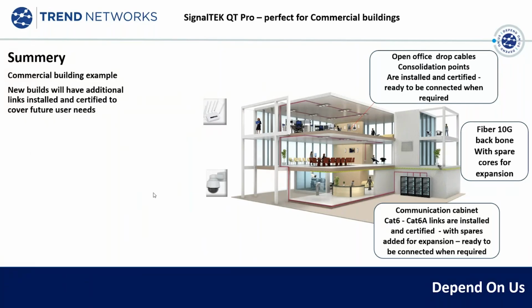In fact, the room I'm working from right now, which is a boardroom, uses floor boxes. If I was to lift the lid off one of those, there's dust in there. There's dust in amongst those connectors. And the example is this would have been certified, handed over to us. However, as we make those links live, has that dust contaminated those links? This is where QT is really, really important.